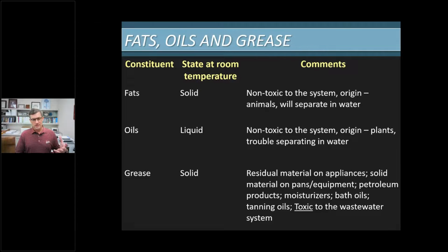And I would say this not only impacts septic tanks, but all the way up to the largest wastewater systems that are out there. Fats, oils, and greases can be a huge detriment to those systems because, depending on, again, if you're in the north or the south, they can cause huge problems with blockage. As it gets colder, they will turn to solid and they'll block up lines. A lot of your floats, as you saw in that tank earlier, those floats can get stuck with fats, oils, and greases. It can be bad.